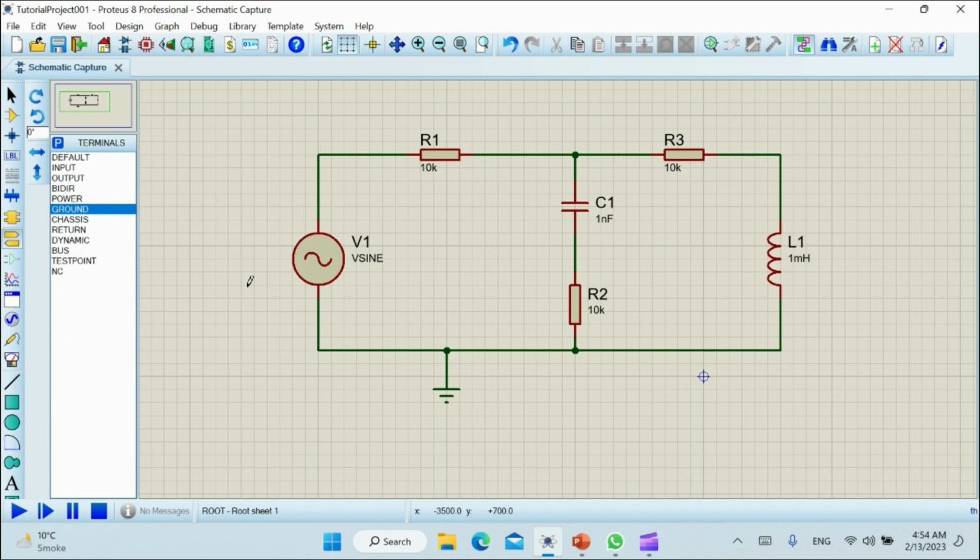So how to edit the properties of any component? Firstly, we should go to selection mode. Remember, firstly we should go to the selection mode. So I am in selection mode now, with my mouse simply a pointer. Now, if I am to edit the properties of any component within the schematic, first I hover my mouse over it, and it is converted from the simple pointer to a hand, which means that this component is ready to be edited.